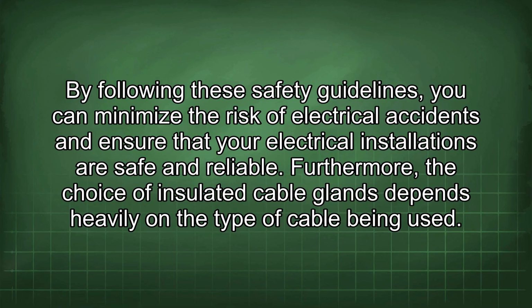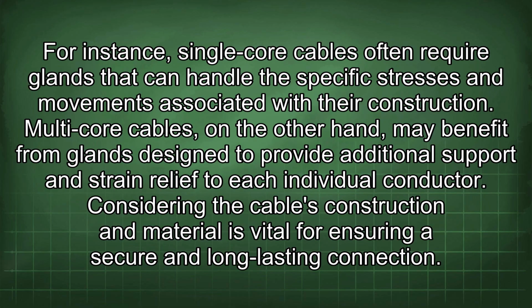Furthermore, the choice of insulated cable glands depends heavily on the type of cable being used. For instance, single-core cables often require glands that can handle the specific stresses and movements associated with their construction. Multi-core cables, on the other hand, may benefit from glands designed to provide additional support and strain relief to each individual conductor. Considering the cable's construction and material is vital for ensuring a secure and long-lasting connection.